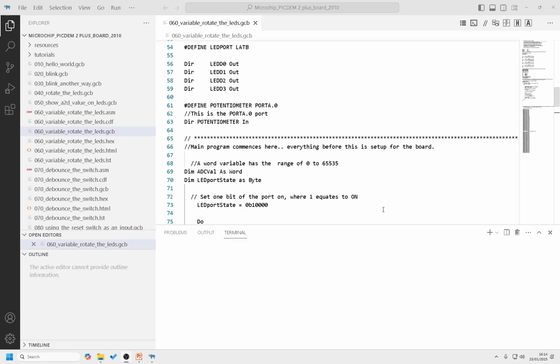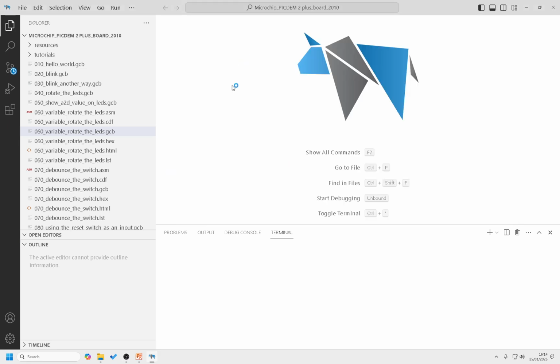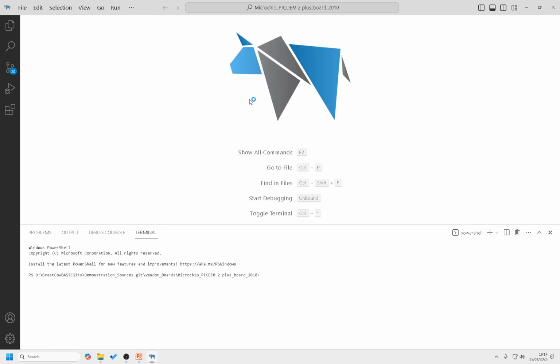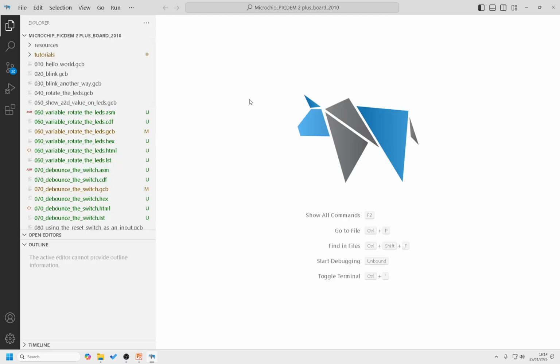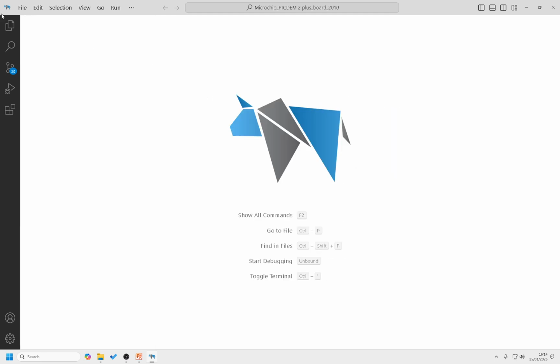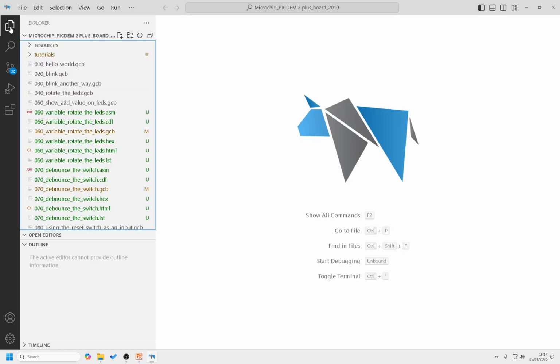And now we've got a program. That's the one we're going to be using. And then we've got all our files on the left-hand side. But if they weren't there, press on that bottom window. We'll say open like that. You can go Control B, and that will open it. You can also press top right-hand corner of a little Explorer icon. It's the same. Open up program 60.